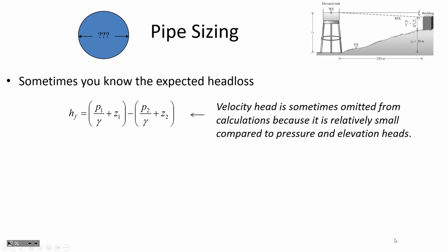That's exactly the same thing I was telling you on the first day of class, how the plumber at my house was suggesting a 1/2-inch pipe. I ended up going with a 1-inch pipe so that I can have every tap open and still have good water pressure. So in this situation, if you had a building and you're trying to have water flow from an